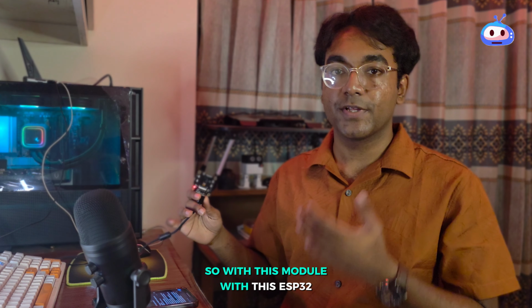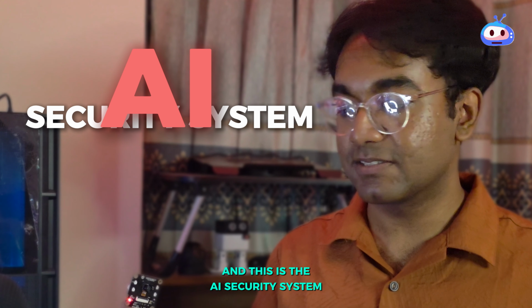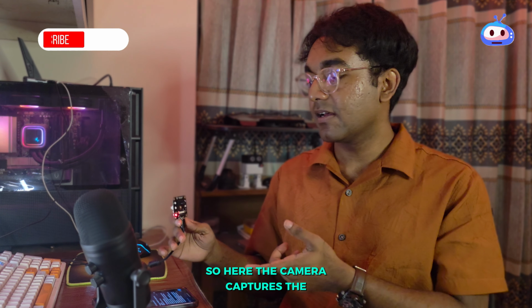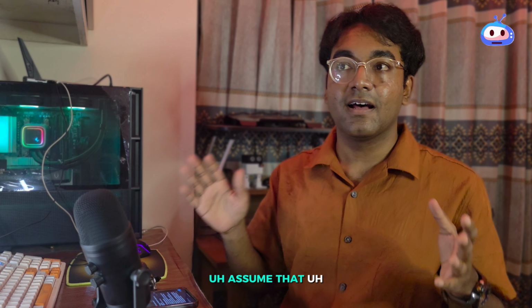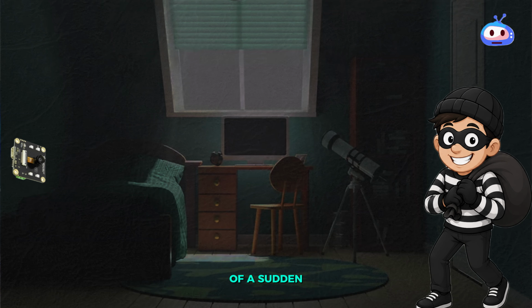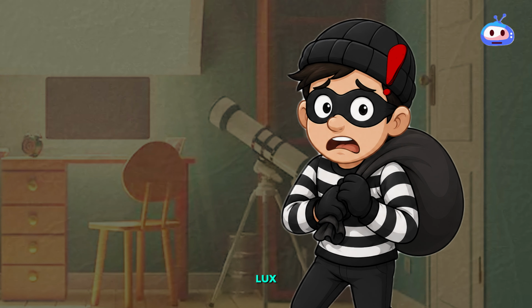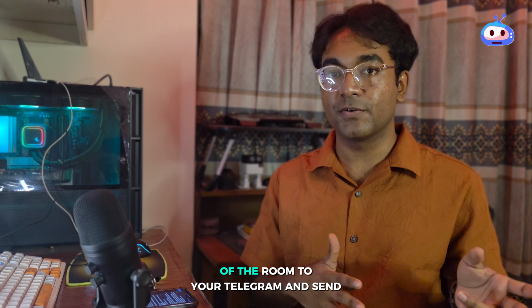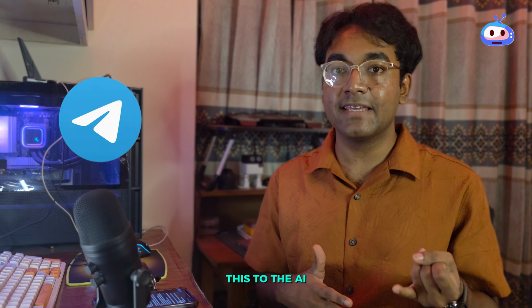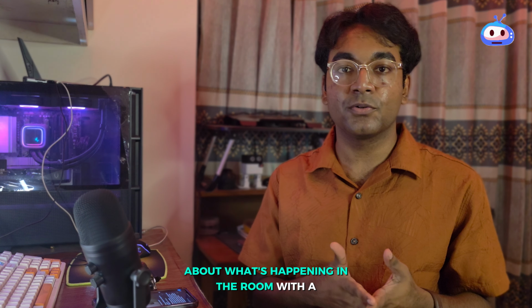With this ESP32-S3 AI camera module, I have created a security system, an AI security system. The camera captures an image of the room if the light changes. Assume you place this camera in a room with the lights off, and all of a sudden a thief enters and turns the light on. It will detect the lux value change using the ambient light sensor, then send a photo of the room to your Telegram and to the ChatGPT API, and it will send you a detailed summary of what's happening in the room.